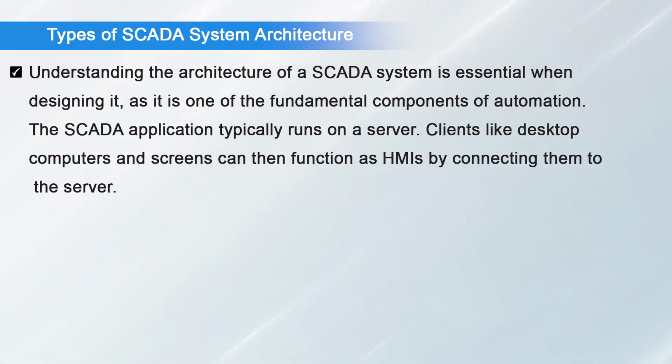So, understanding the architecture of SCADA system is essential when designing it, as it is one of the fundamental components of automation. The SCADA application typically runs on a server, and the clients like the desktop computers and the screens then function as human machine interfaces, HMIs, by connecting them to the server.